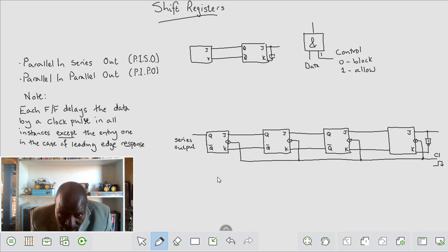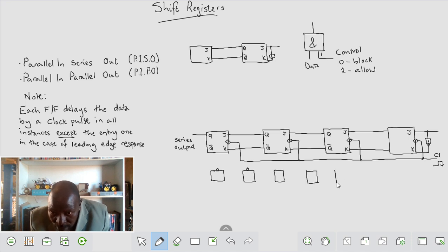What I need to do is decide here for each one, either I'm setting, or resetting, and I explain why in this case we cannot use AND gates. The 0 will immediately try to set and reset both. So each one will need 2 NAND gates, one for the ability to set, the other for the ability to reset.